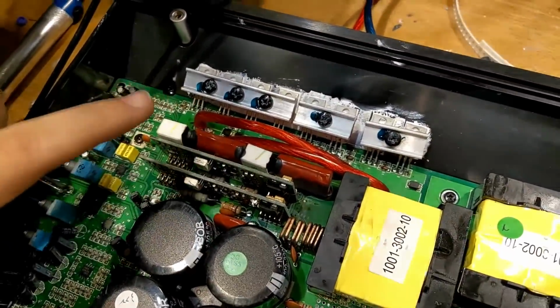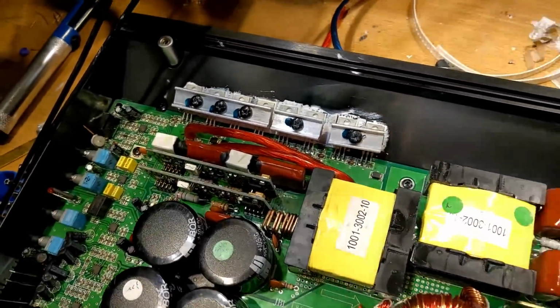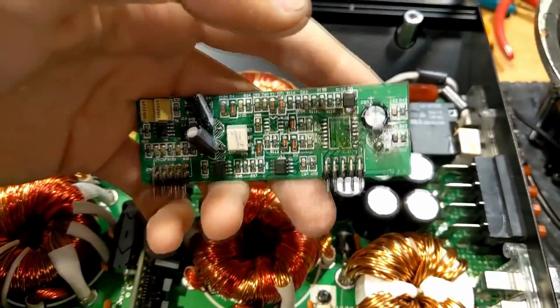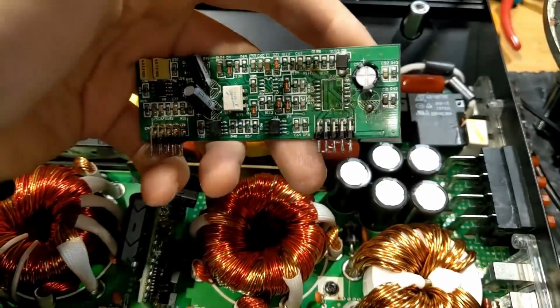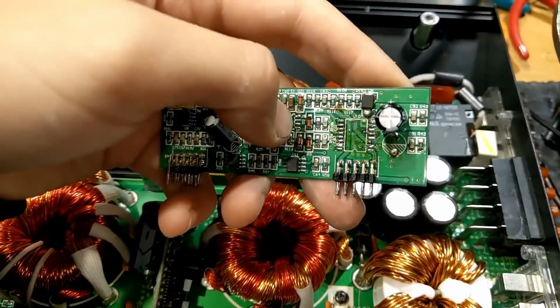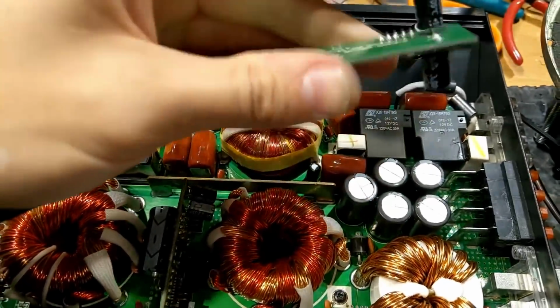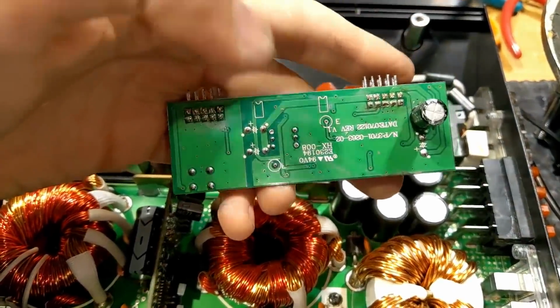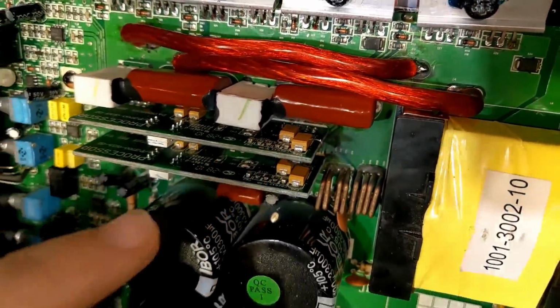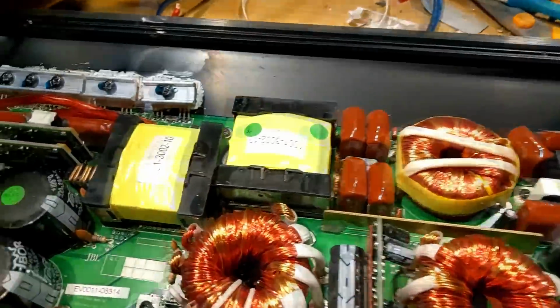Now, these chips, one of them was really bad. Just to give an example of what I replaced, here's an example chip that's similar. Had to replace the main drive IC chip, had to replace the high-low side PWM conversion chip. On the back, there was a couple of resistors. This one doesn't have anything on the back, but on the back there's a couple of resistors I had to replace at the top just here, 10R resistors, and there was also a couple of traces that I had to rerun because of that massively exploded area.